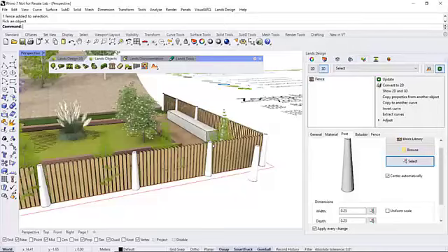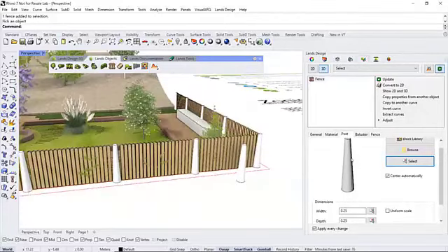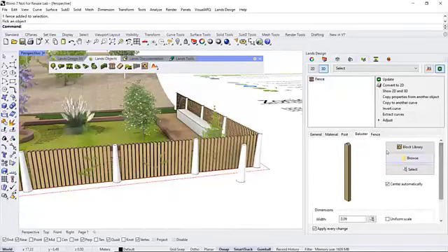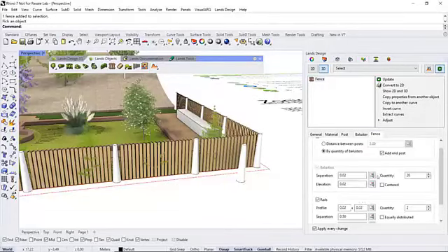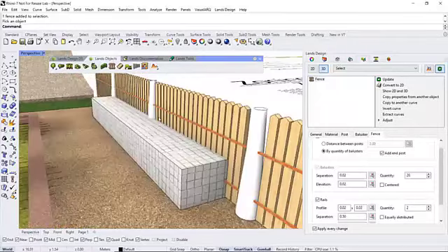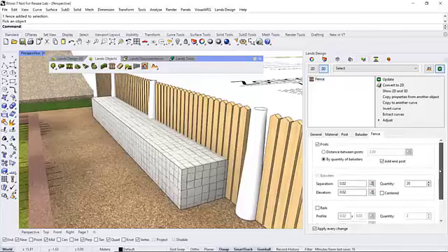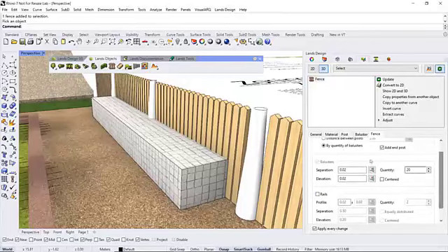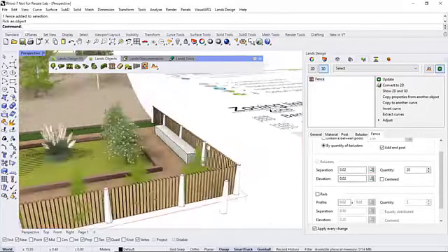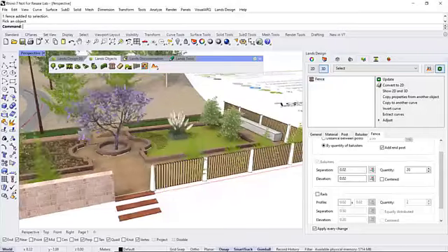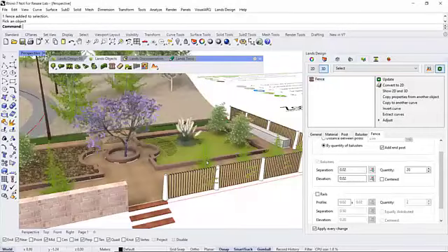So you can customize the appearance of this fence in a parametric way with all these options. We can do the same with the baluster, and here are all the different options for these rails. We can change the profile, or we can just disable it, and explore all these features to control the way this fence will look.